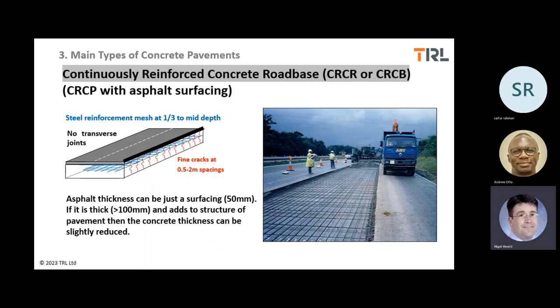Okay. I would say that you want cracks closely spaced, because if they are further apart, you'll get more movement at each crack. So it's good to have closely spaced cracks, about 1 meter spacing, approximately. Some will be half, some will be up to 2, but it's better to have closely spaced cracks more often.